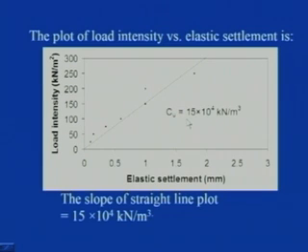Now, as we were discussing last time, when you are finding out these constants in the field and then applying them in case of foundation, you have to apply some correction measure, because their values depend on the contact area of the block foundation and the soil.